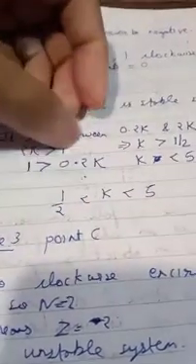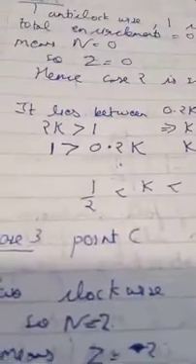And in case 2, the critical point lies between 0.2k and 2k. So using this we say that 2k is greater than 1, and so the value of k will be greater than 1 by 2, and 1 is greater than 0.2k, so k is less than 5, because the critical point minus 1 plus j0 lies between 0.2k and 2k. So 1 by 2 is less than k is less than 5. This we have got. So already we have got our answer. Our answer is option B. We can see that in option B this criterion is given. But we will solve further.